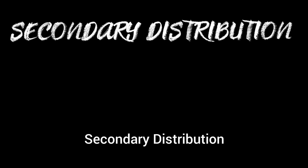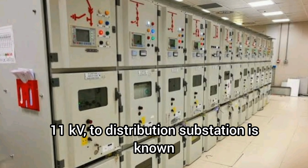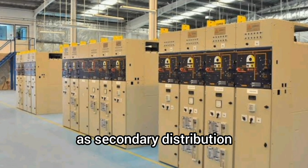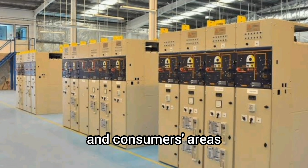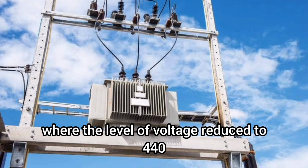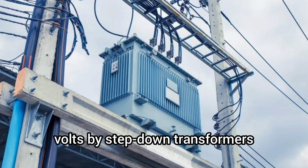Secondary distribution. Electric power is transferred from the primary distribution line, i.e. 11 kV, to the distribution substation, which is known as secondary distribution. This substation is located near domestic and consumer areas where the level of voltage is reduced to 440 volts by step-down transformers.